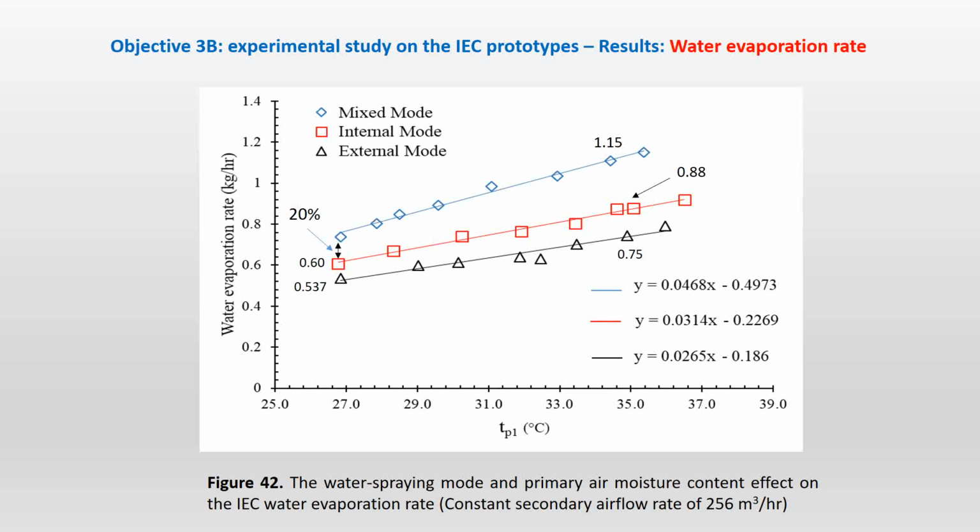Yes, I did the uncertainty analysis not only for these averages. I took readings for 5 minutes and then averaged the value and put it here. Because the reading keeps changing every 10 seconds, it's not going to be constant. It goes up and down a little bit. In all the cases these are average values, but for the whole readings, I have done the uncertainty analysis using the statistical method.